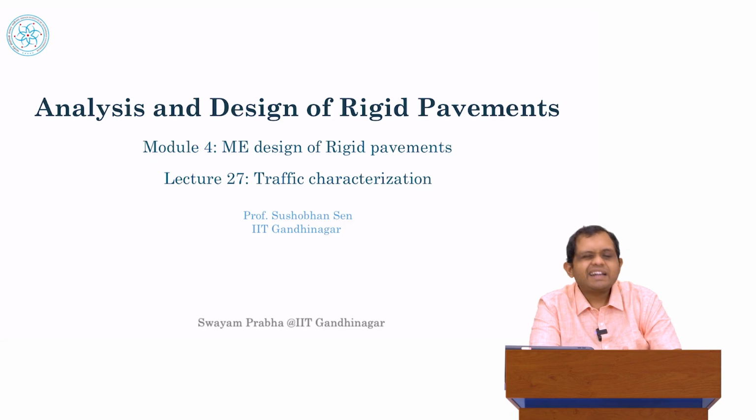So in design, we know a little bit about our final answer. We have to somehow create or design a pavement which gets us to that final answer. And that's why in module 4, I took time in module 2 and 3 to explain analysis, because design is eventually an iterative form of analysis. We start by choosing some type of test section, some materials, we make a decision on climate, for example, and then we calculate our distresses and then we compare them to the performance.